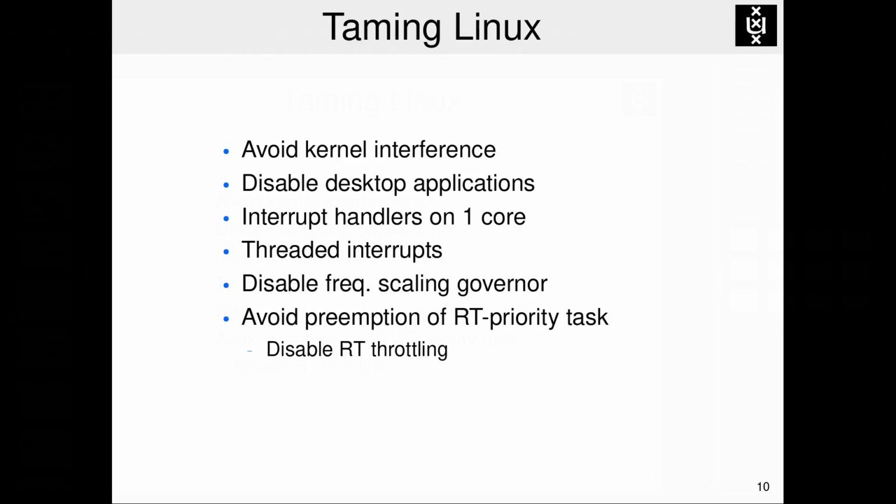Linux is known to not be the best OS when dealing with real-time systems, but it's a constraint of this project that we can't get rid of. Therefore, we configured it in a way that helps us regain some control on time. The idea is to remove as much interference as possible, this interference coming from the kernel tasks and the system tasks.